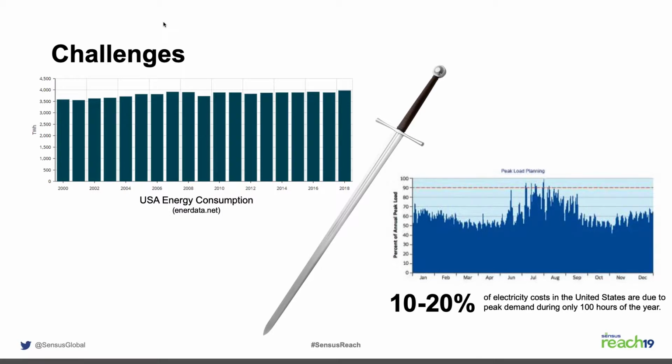But at the end of the day, what you're having to balance is, do I get more benefit in reducing my voltage and saving from those peak times as I do from power loss that I'm not going to be selling to my customer? And so this is very dependent on the nature of your feeder, the nature of your power purchase agreements. And so when you pursue something like this, I don't want to encourage you and say, all right, you're ready to go, you're going to save X amount of money immediately, because that may not necessarily be the case.